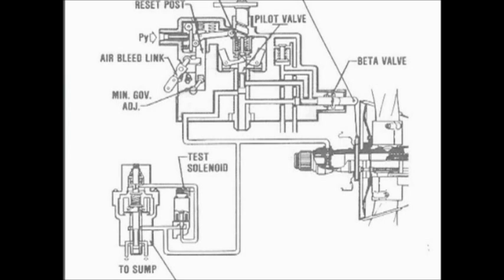This permits the combined forces of the counterweights and return springs to move the blades towards a coarse pitch position, absorbing the engine power.